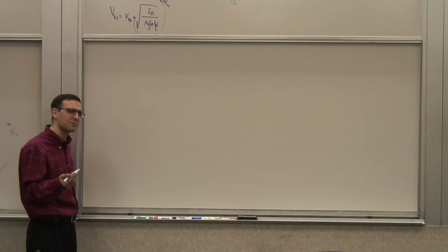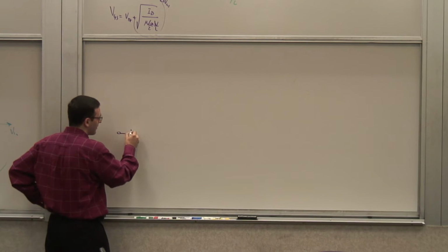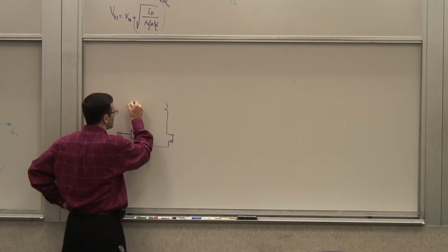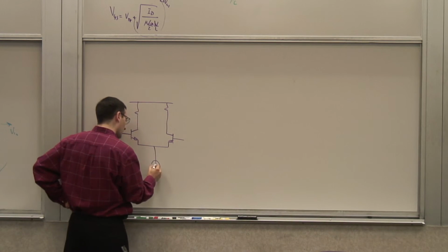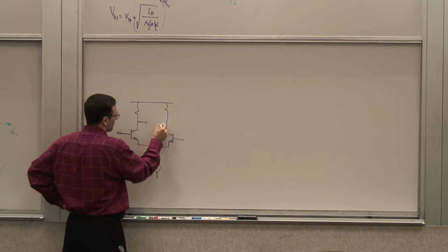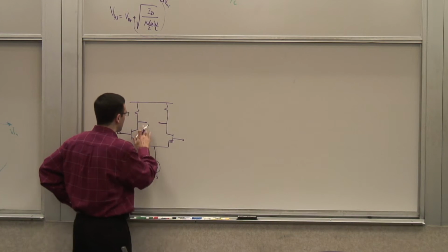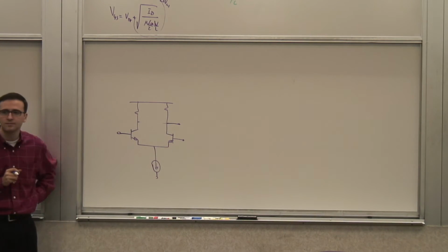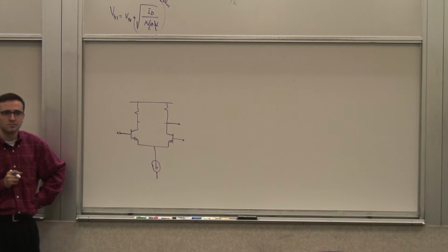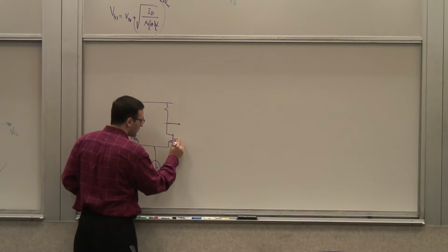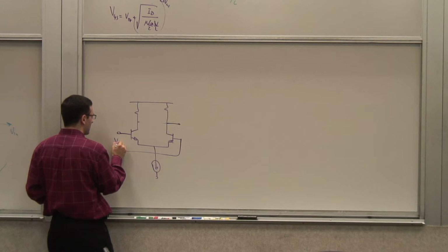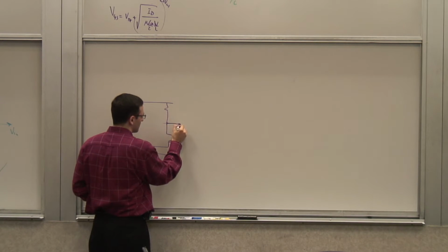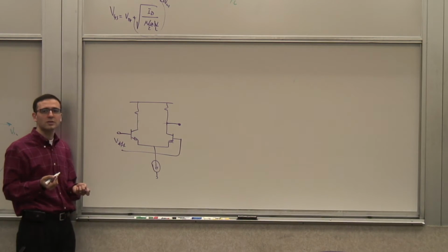So you ask me, well, what's the big problem? If you have a differential input here, right? And you had the differential output. Now if I just look at one of the outputs, it would be a single-ended output. So what's the big deal? There's no big deal, that's true. I mean, you can always use that as a conversion of a differential voltage to a single-ended voltage. But what's the problem with doing this? Yeah, you're losing half of your gain.